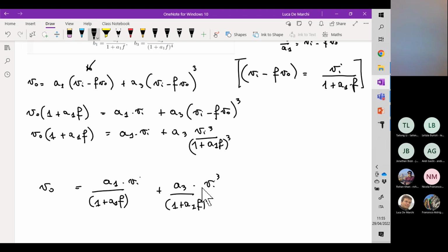What happens if we do have feedback? Let me resketch the previous circuit. The first configuration is based on a certain source voltage corrupted by a noise or interference source here, and then we have the amplification. The signal-to-noise ratio can be estimated at the input, and this is the relationship between the signal value with respect to the noise value.